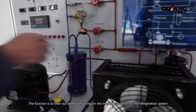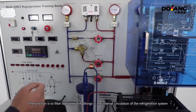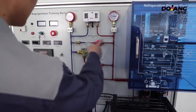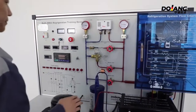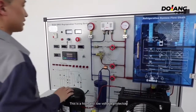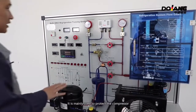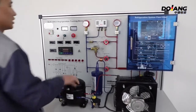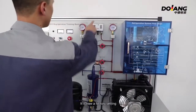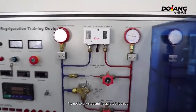This is a filter. The function is to filter out some dirty things in the internal circulation of the refrigeration system and prevent the throttling device from clogging. This is a high-pressure meter. This is a high and low voltage protector. It is mainly used to protect the compressor. You can set value on it. It's now a factory setting. Try not to ask students to adjust this value.